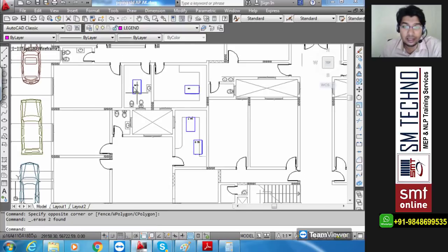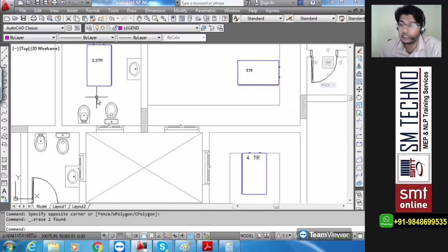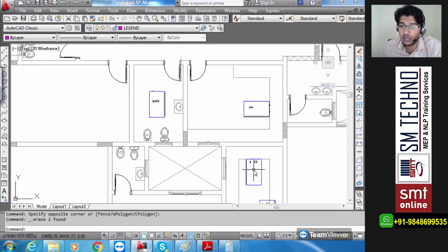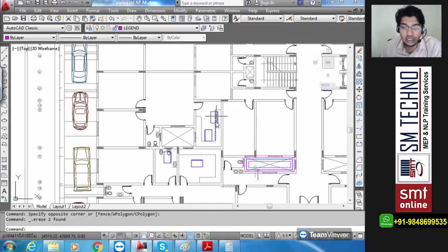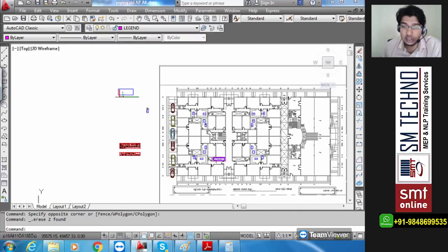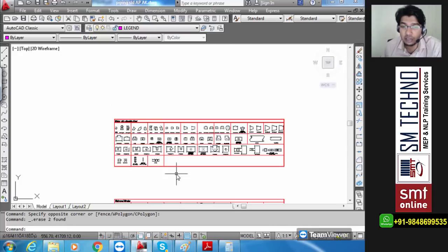These AHUs have their capacities mentioned: 3.3, 5 TR, 4 TR and 3 TR. Fine. So you can see these are left empty. This much space is for assignment. You give your own quantity for the AHU, decide your own pipe size and let me know how you have done the connections. Is it clear? For that, I have left these 4 AHUs in 4 different places unentered.